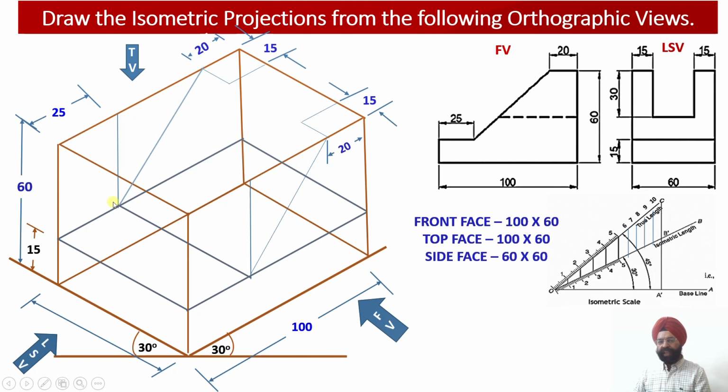Now I have obtained the bottom line, that is 15 millimeter above the base over there. Now I need to mark this particular web, right? In order to mark this particular web, please see what I have done. I have drawn this flat portion. Please check. I have drawn this flat portion 15 millimeter above this reference line which I had drawn to represent the bottom of the web over here.